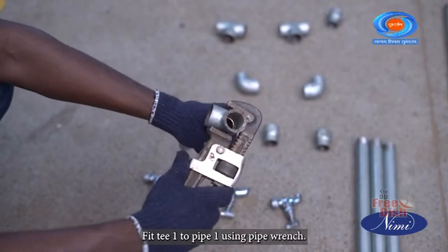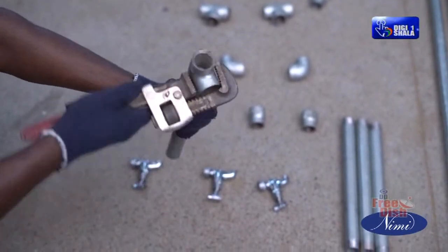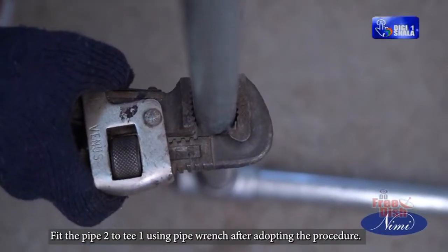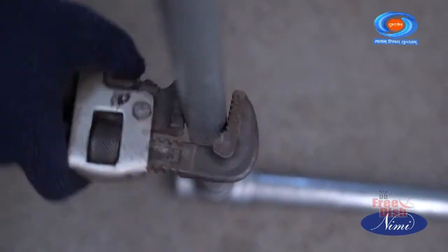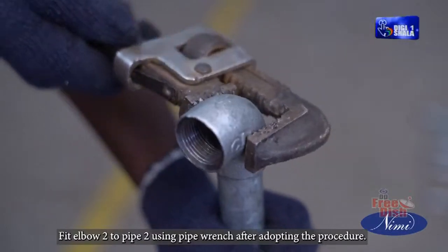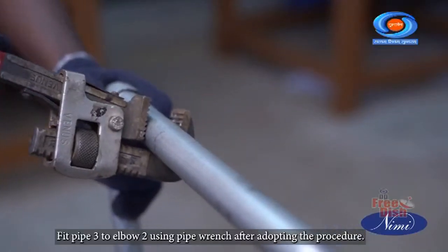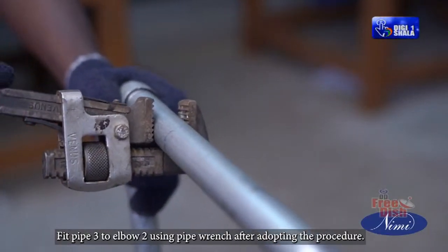Fit T1 to pipe 1 using a pipe wrench. Fit pipe 2 to T1 using a pipe wrench after adopting the procedure. Fit elbow 2 to pipe 2 using a pipe wrench after adopting the procedure. Fit pipe 3 to elbow 2 using a pipe wrench after adopting the procedure.